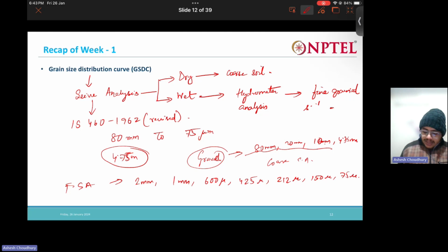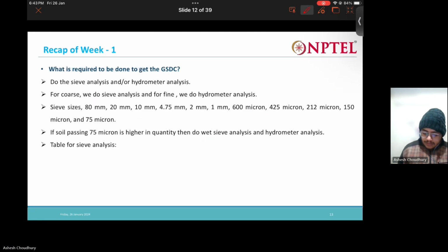See, I've written here: do what is required to obtain the grain size distribution, the sieve analysis or the hydrometer analysis or both. For coarse, we do the sieve analysis, and for fine, we do the hydrometer analysis.